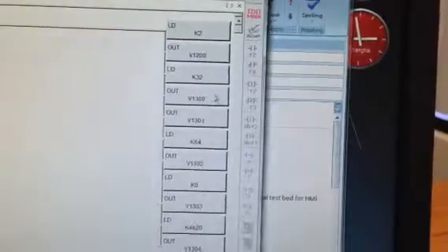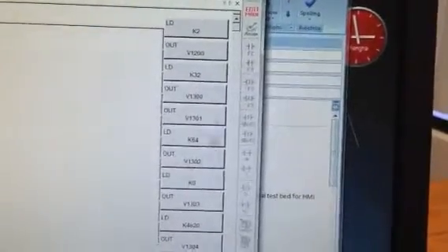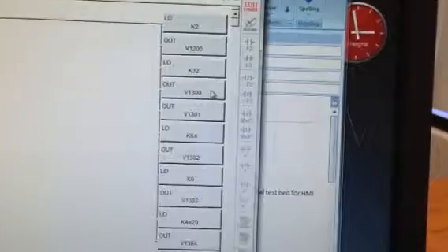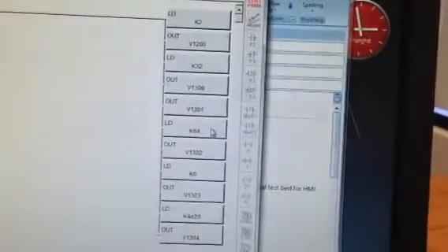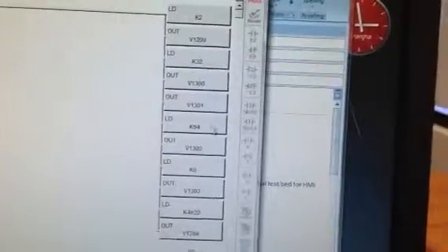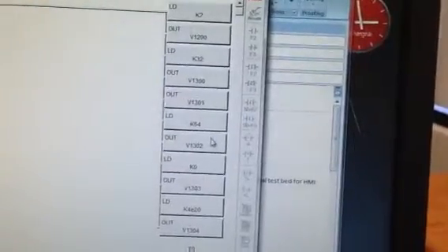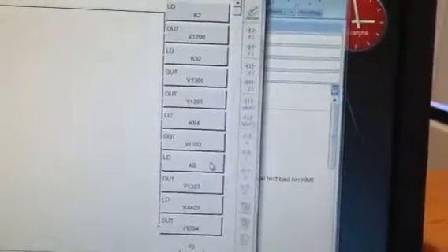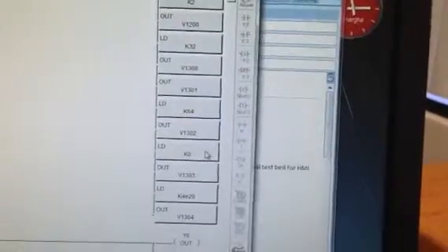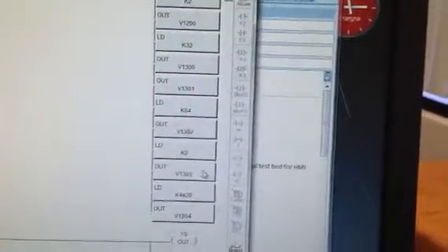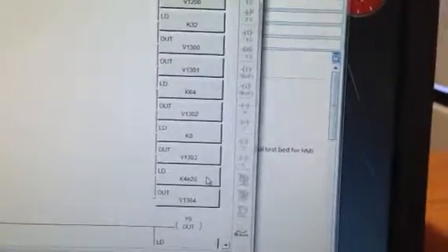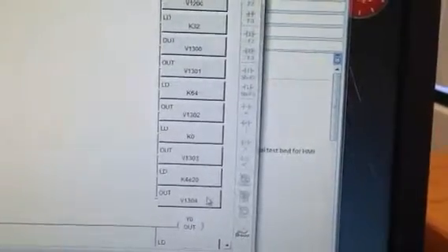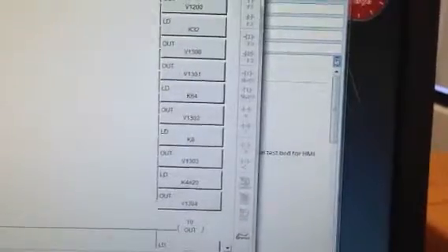Later on, we'll write all these contiguous memory locations over the Modbus into the drive, and that'll set up all the move parameters. 64 hex is our velocity, and that goes into 1302. 0 is the upper word of the move distance. That'll go into 1303. The lower word is 20,000. That's 4E20 hex. That goes into the last register of the block transfer for the move parameters.